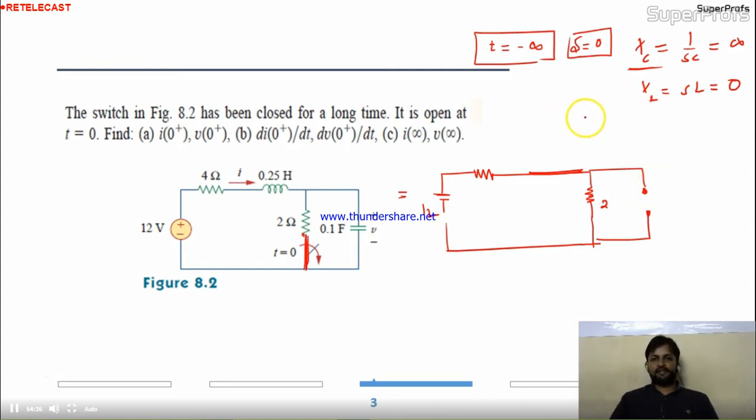You can see this. The circuit was working in the steady state, I told you, t equal to minus infinity. If t is infinity, s is 0. If s is 0, you know the formula, so you can get the reactance. Capacitive reactance is nothing but the open circuit, I opened it. Inductive reactance is the short circuit, I shorted it. Everything remains the same.